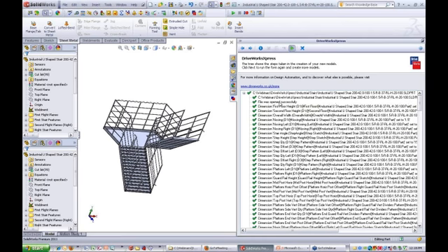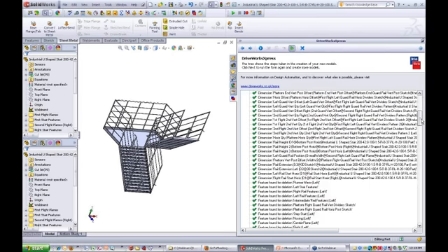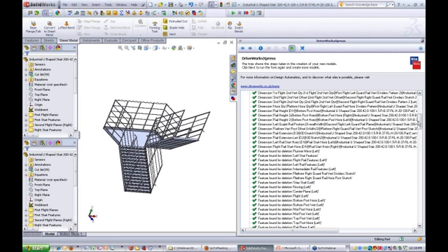The file was opened successfully. The dimensions were controlled. A bit hard to see. It actually says it's set to the value that we put in. That's all controlled by rules. We'll see in a moment. As you scroll down, it talks about dimensions there. Then we come into features. In many cases, features were deleted based on the data we put in. Features can be deleted or suppressed or unsuppressed.